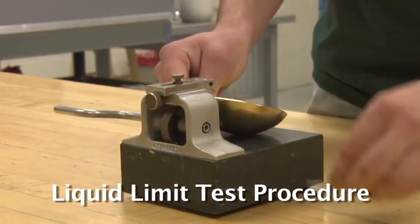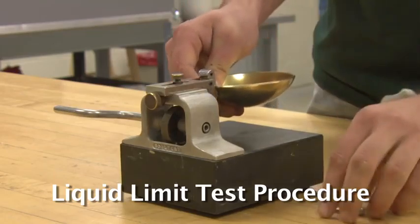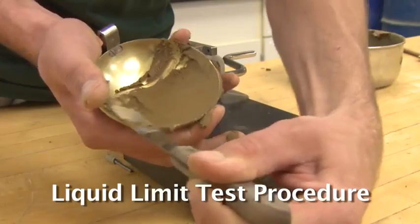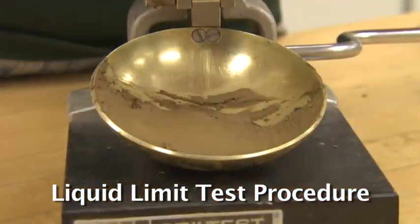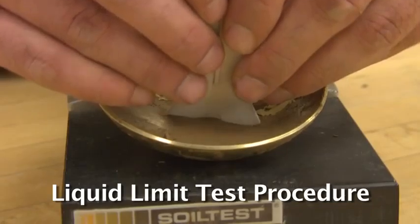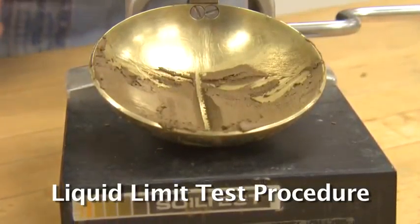Thoroughly clean and dry the cup. Evenly spread a moderate amount of soil into the cup to create a soil pat to be tested. Using the grooving tool, create a straight groove through the center of the soil pat. The shoulders of the grooving tool should just scrape the surface of the soil pat.